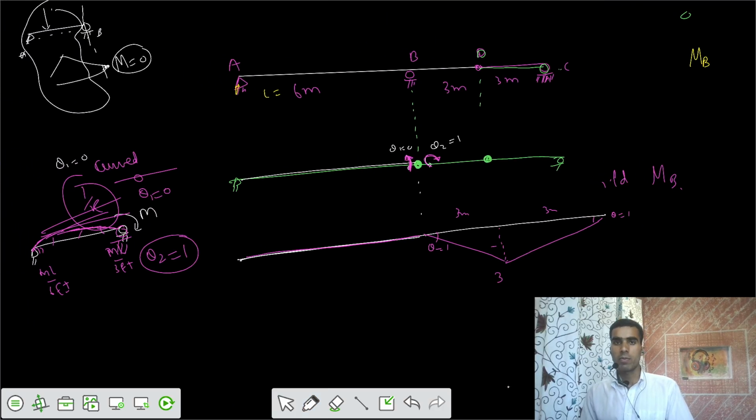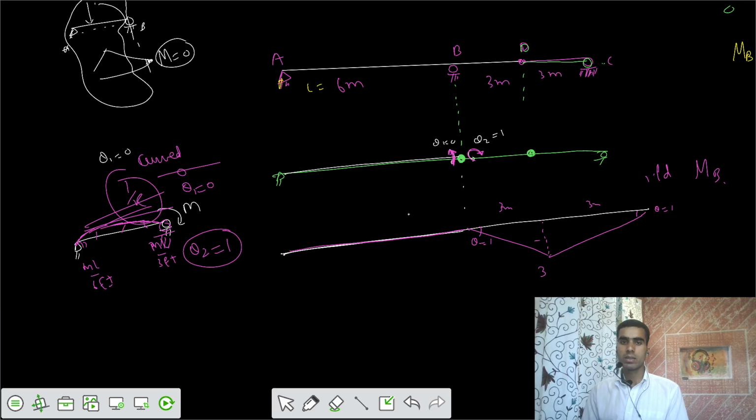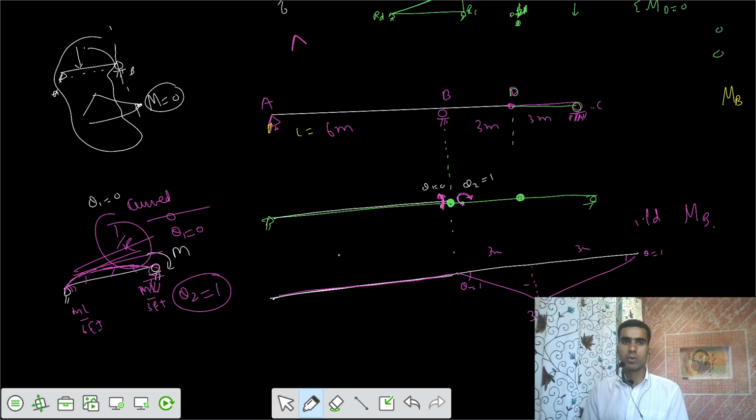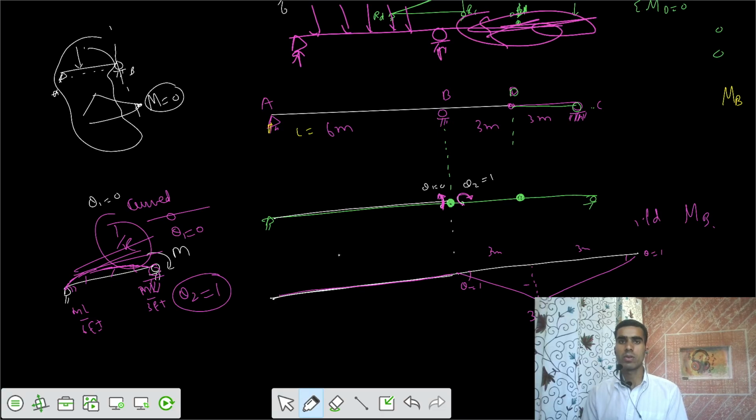That means if you apply a load, it's similar. We already have the conclusion that once we have a simply supported beam, the load here is entirely taken by this support and this one, such that the moment here is 0. So there is no load here anywhere. We say that it is a simply supported beam, and the moment at B is 0 for all values of x, up to this point.